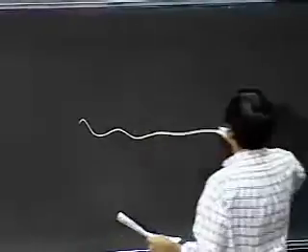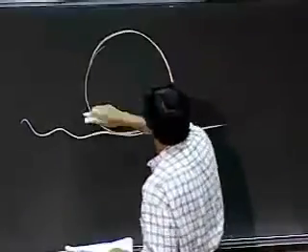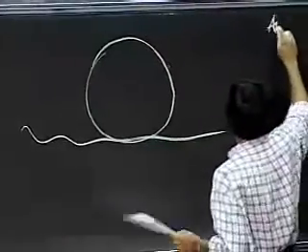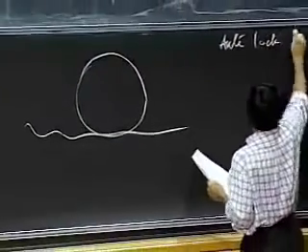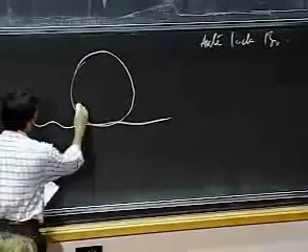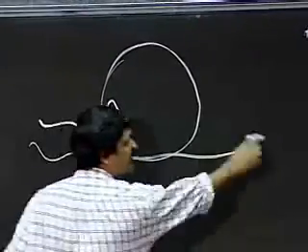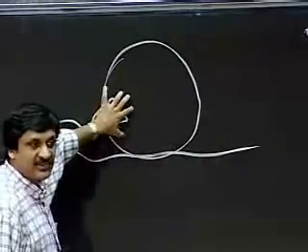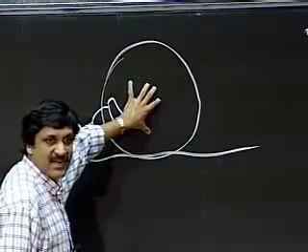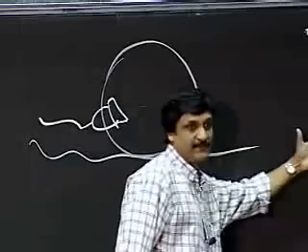So this is a road here. Let's look at anti-lock brakes. This is my tire, and let's say I have a set of disc brakes here. As the car is moving forward, if I apply the brakes, the tire stops rolling. But if I apply the brakes too hard, it can lock up the tire and the whole car can skid.